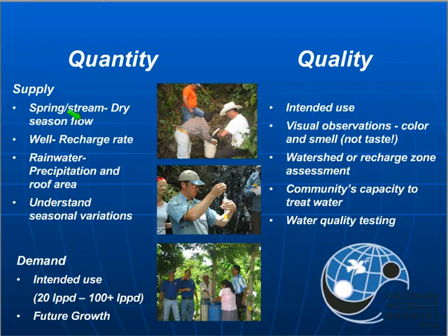And this was a big project, I think it was $80,000, and three different communities were going to benefit from it. And the source had dried up after all of that information had been collected. In the rainy season, there was so much flow, no one thought that they even needed to worry about it, but because the people doing the design hadn't been there in the dry and wet season to understand those fluctuations, it was a huge problem that required quite a bit of rework and redesign and having to fundraise over again because of that.